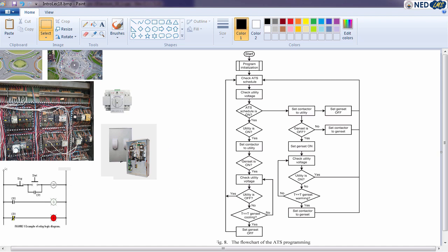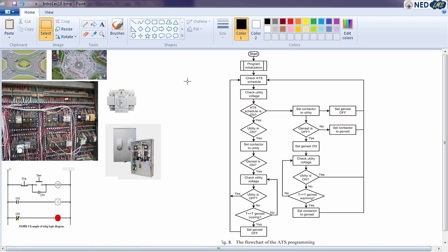Now if we develop this flowchart behavior using relay logic, that means that all the hardware settings and all the timer settings have to be done by hand. I mean, we need to develop all these things, and whenever a change is required in terms of timers or in terms of some kind of relay logic, we need to actually make or break physical connections in these wires.